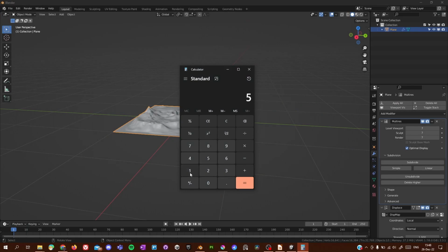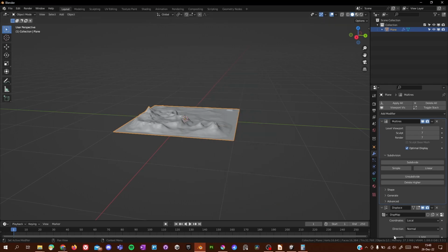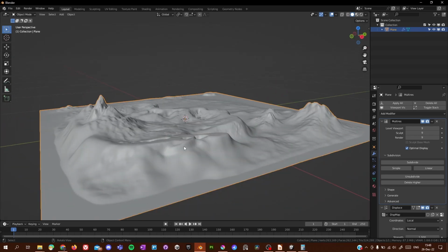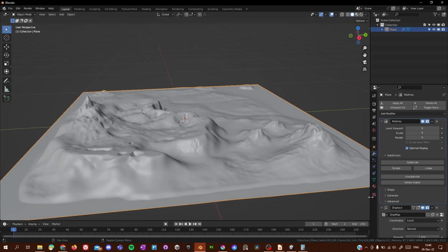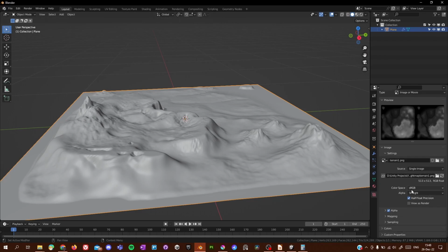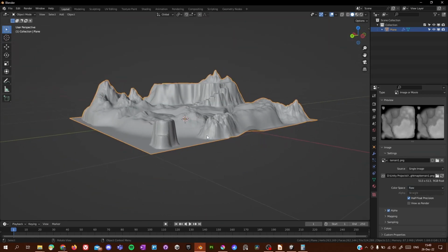So what we'll do is we'll basically multiply, and we get this 262 thousand vertices. So simple, it's 263, and yeah, that's our number. So that's well and done, but as you can see, the height is not correct. To correct that, we'll shift to the textures tab, and then instead of sRGB, we will change it to raw, and that should basically give us the correct height.